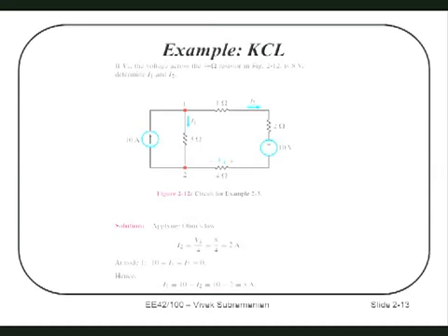Okay? Does that same current, I2, go through the 10 volt voltage source? Yes, it has to. There's a node here. Current going in, must come out. So this is what we'll call current continuity. Whatever current goes in has to come out. So in this case, I2 does in fact go through the 10 volt source. Okay?